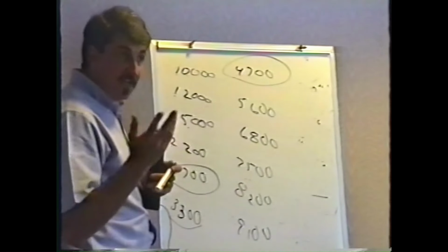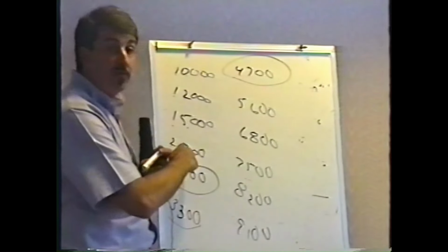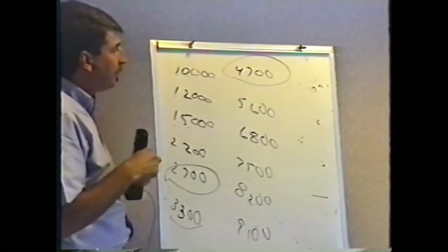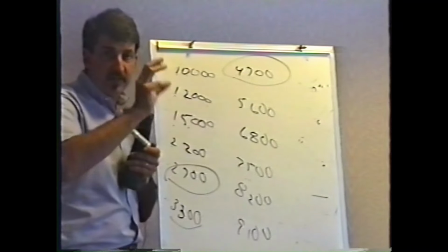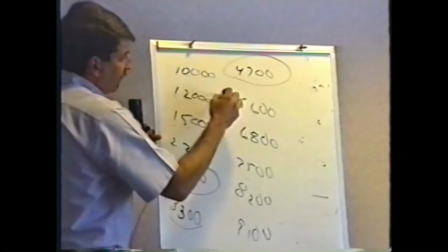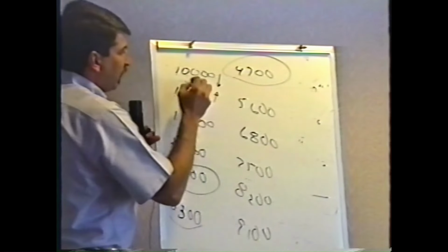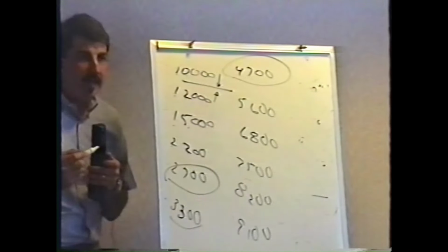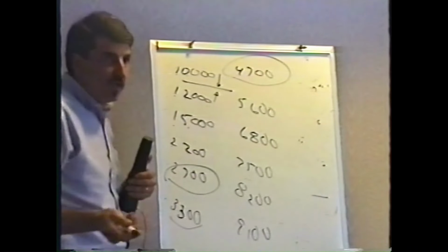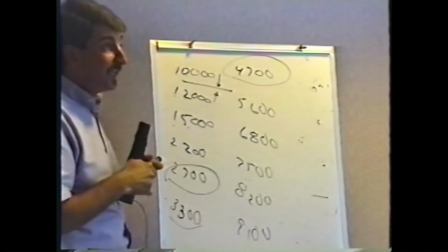But you hardly ever see 2K resistors. You see 2,200 ohms, you see 2,700 ohms. You don't see the 2Ks. And the reason you don't is that, remember the tolerance, the plus and minus part of this whole deal. If you go up a little bit in tolerance this way and down a little bit in tolerance this way, right in the middle is kind of where they meet anyway. So you don't see every value under the sun. So it's pretty easy after a while.